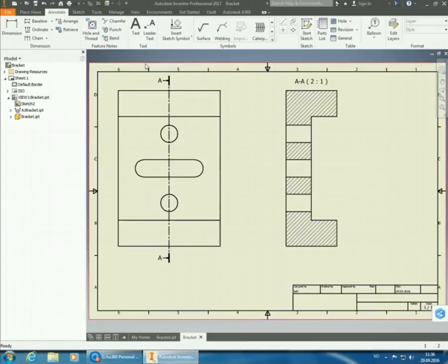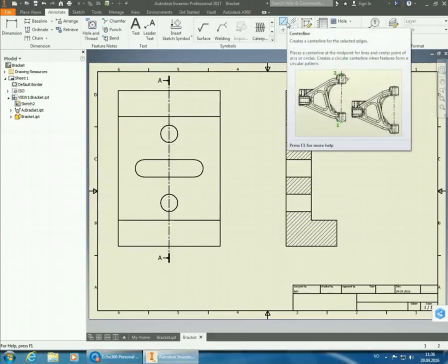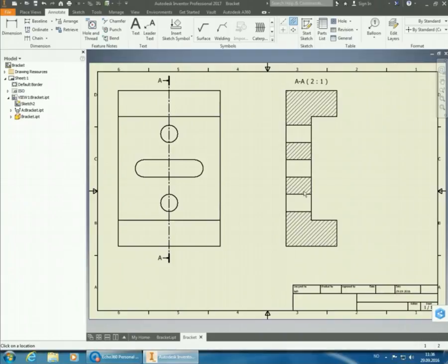So we're going to put in center lines, but here we have center lines going through these holes, so we can use the one where we just mark the edges of the hole so that we get a line going between these. So the center line bisector, it's called. So we put this one in on all three here.